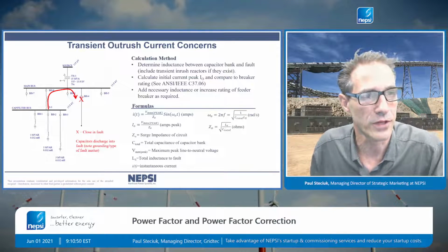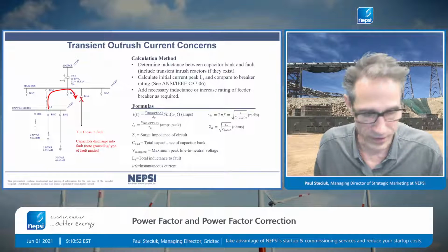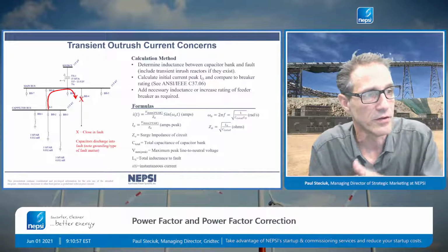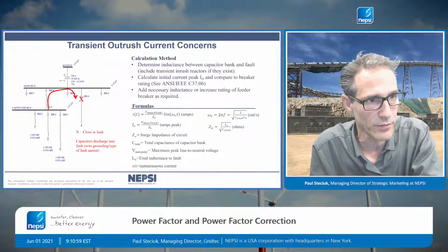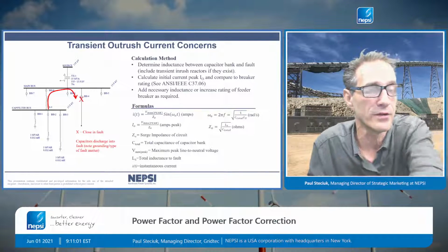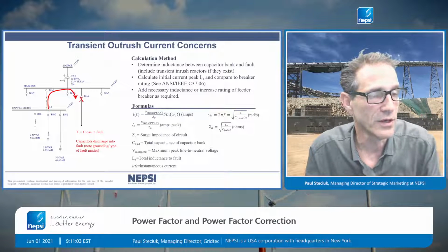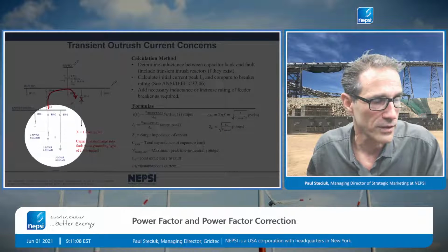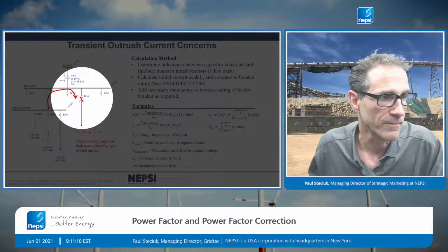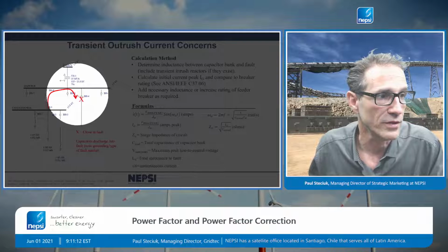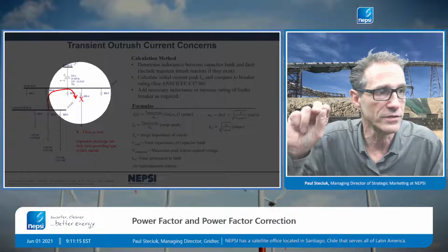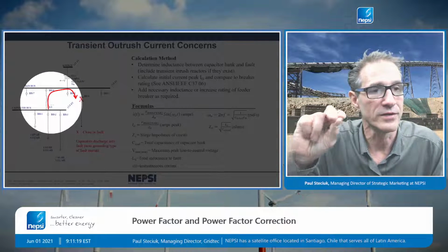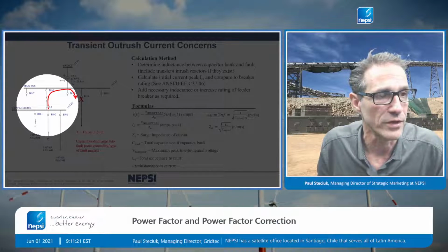But at some short period of time later, because of the desire to clear a fault and then to re-energize for reliability issues, the BH4 breaker recloses automatically, or maybe a guy goes out to the substation and closes it manually. But the fault is permanent, and all of the charge within this capacitor bank dumps into that point there. There's very little inductance between that point right outside the substation, basically on the low side terminals of the BH4 breaker, and we exceed the momentary rating of the breaker.